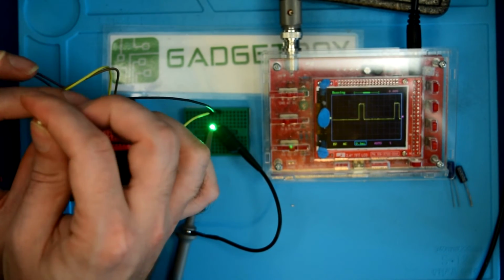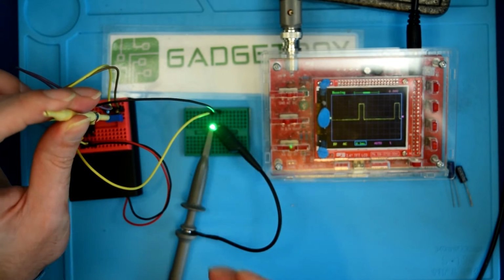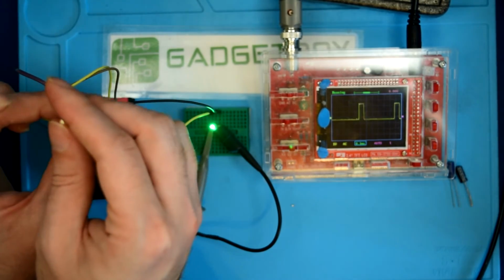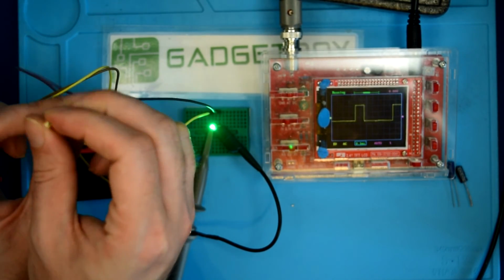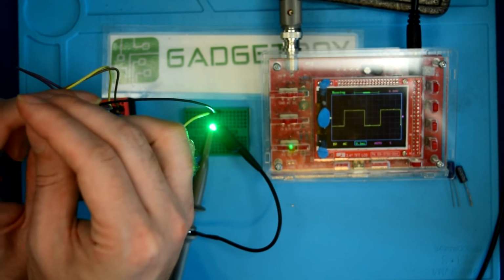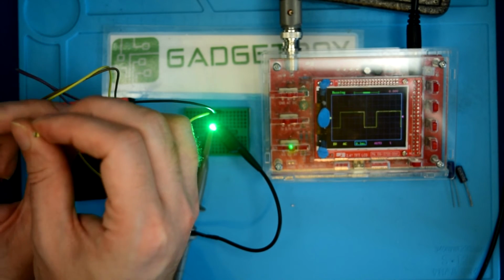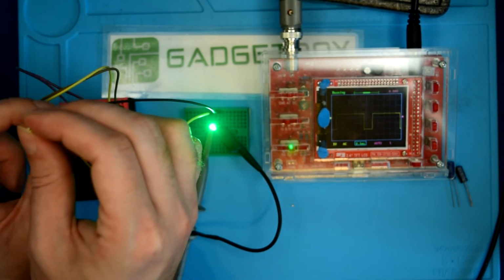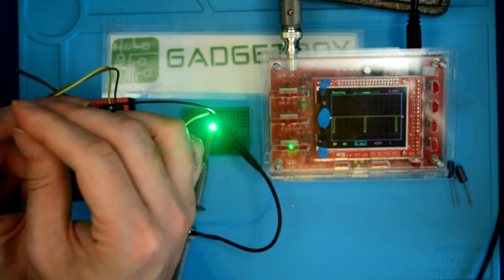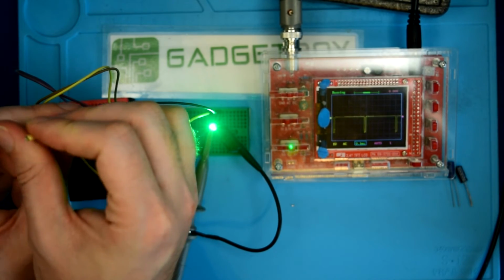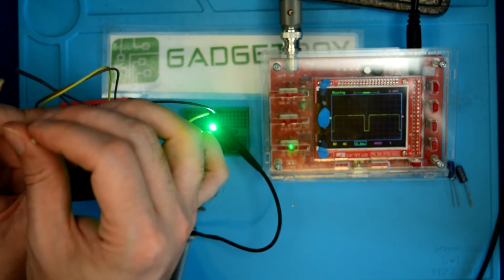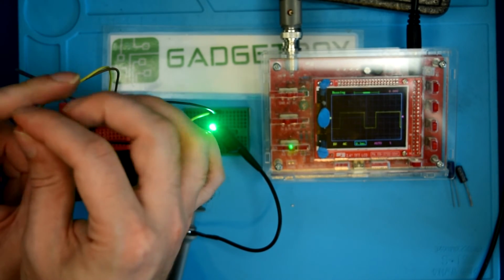Bring it all the way down to the minimum. And now there's no shimmer, but you can still very clearly see the brightness of the LED change. Now let's bring it up. And this is a very linear way of changing the brightness of LEDs. When you're using a linear driver, the brightness change on the LEDs is actually exponential. But when you're using pulse width modulation, the brightness of the LED changes in a linear fashion. So there's absolutely no shimmer at all.